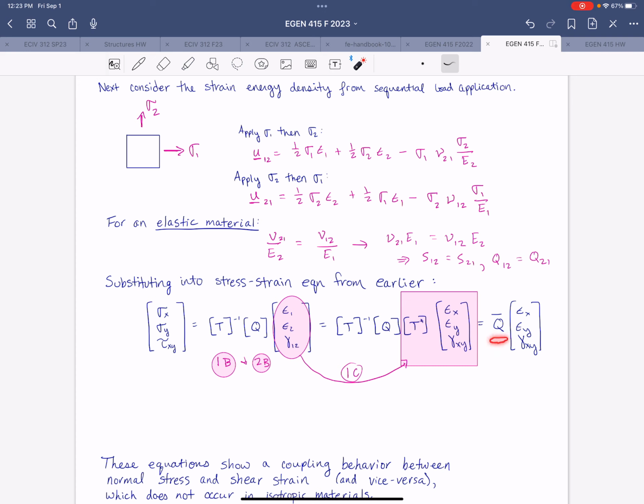And so we're simplifying this 3-matrix product term as Q bar. And if you were working in terms of, in the other world, right, with the S's, then it would be the S bar. And those equations are all written out on the next page of the handout, just for your reference there.